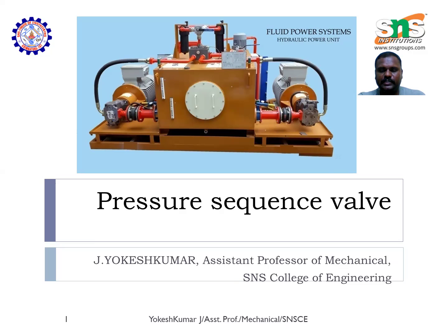The pressure sequence valve is a special type of valve which is used when the systems or motors use more than one cylinder, probably two or three. It is used to sequence the operations or sequence the cylinders in multiple cylinder applications. So that is the concept of the pressure sequence valve.